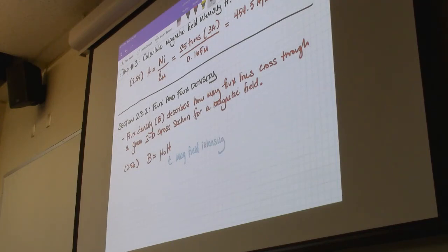We're going to assume it's air. And it makes sense to use mu naught because in 99% of our cases, unless we're talking about an oil-filled transformer or something like that, the magnetic field will be crossing an air gap.